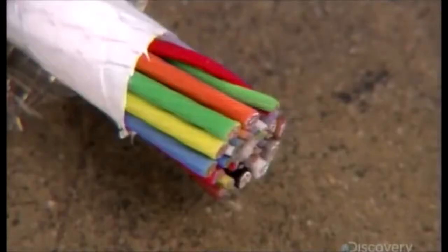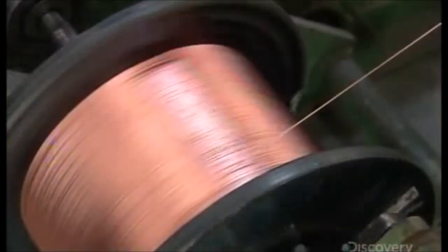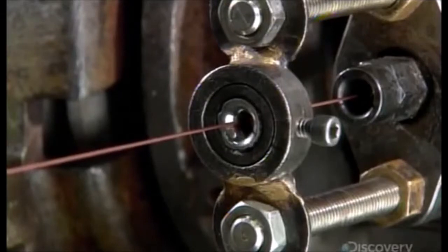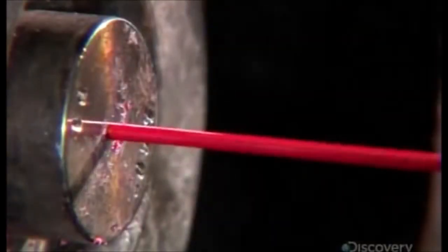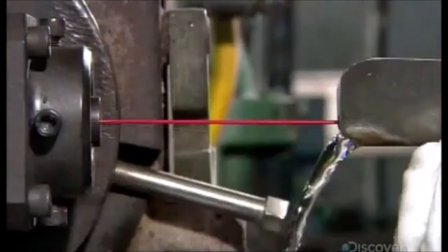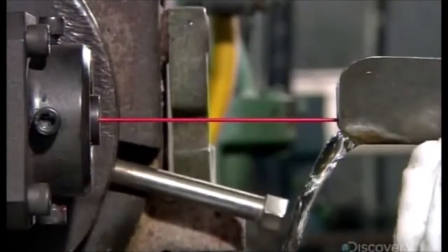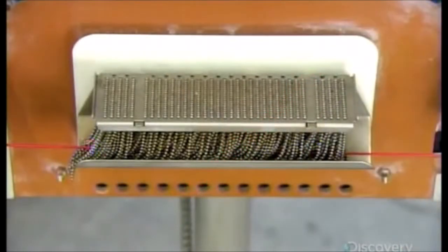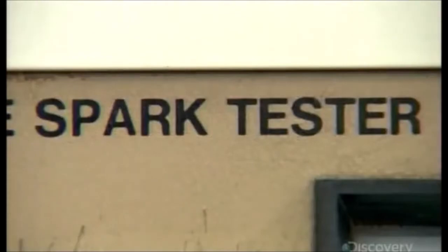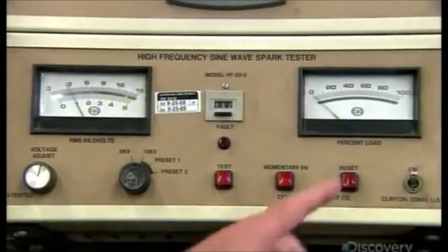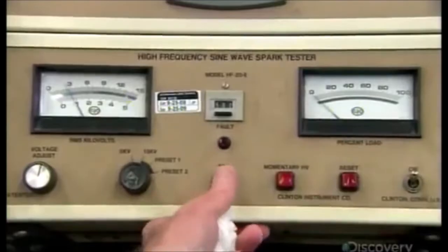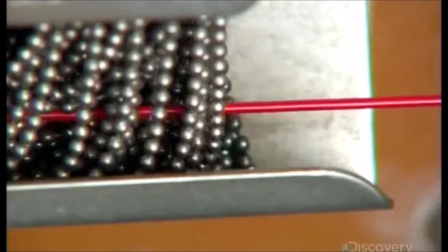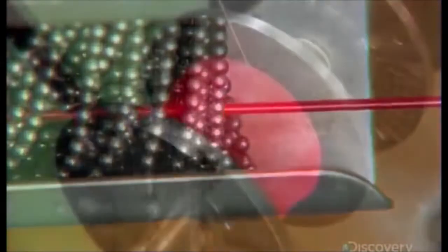At the heart of a cable are electrical wires, called conductors. A conductor begins as a bare copper wire. This extrusion machine coats it in plastic. Chilled water solidifies the plastic around the wire as insulation. This isolates each wire from its neighbors. Every conductor passes through a machine called a spark tester. It runs current through the conductor to ensure the insulation is flawless. If there's even the smallest break in the insulation, the machine will sound the alarm and locate the spot.